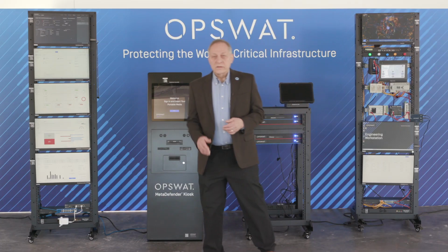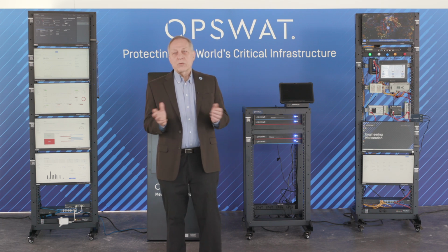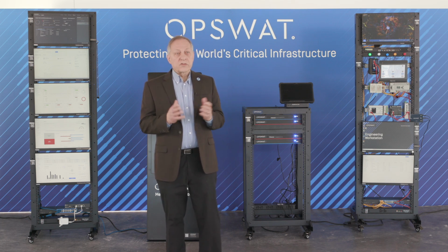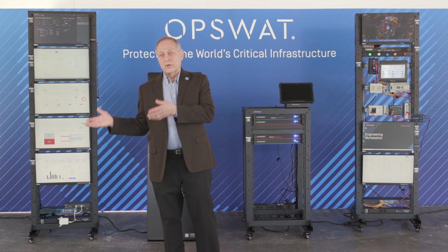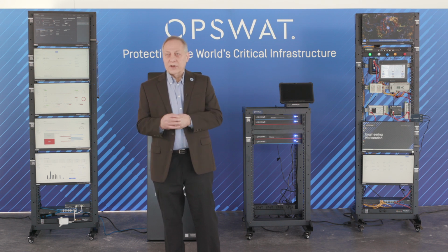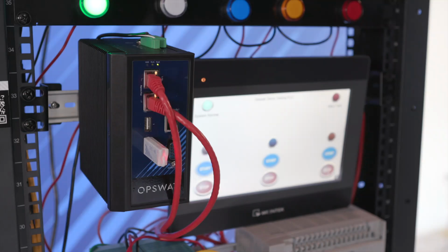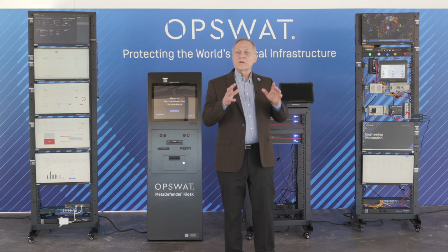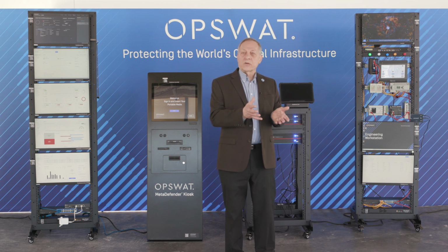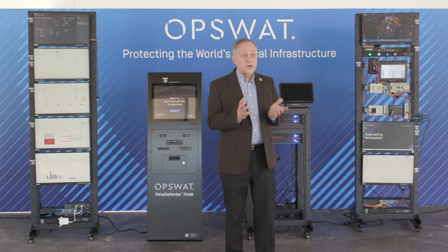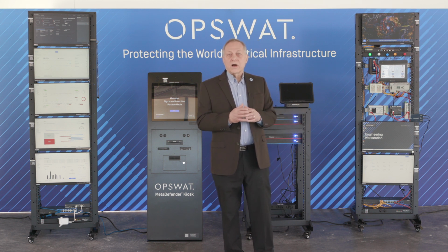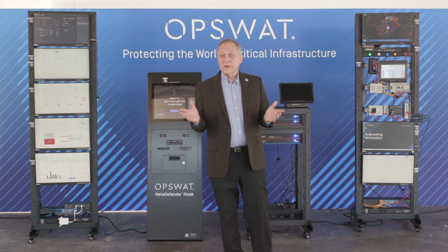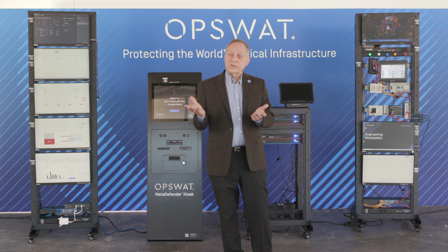A third recommendation is for your OT network to be properly segmented. This is to prevent the propagation of malware from one operational zone to another operational zone, essentially a containment strategy. Again, OT Fuse acts as an industrial firewall. It'll enforce commands to that zone and limit access to that zone to authorized users and only the traffic that's meant to enter that zone. So it does serve as a firewall, and it does segment a normally flat network into operating zones to enforce that security requirement.